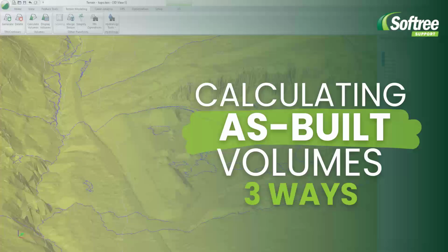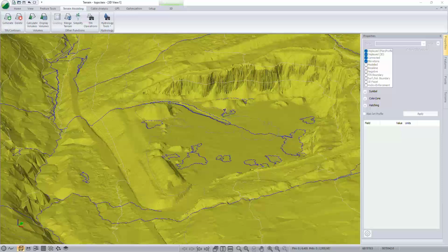In this video we are going to introduce three strategies for calculating as-built volumes. So the first strategy is simply calculating the volume within a single surface. A common example of this is if I had a stockpile and wanted to know how much material was in that stockpile, well, we could delineate the base of it.